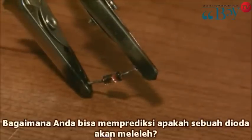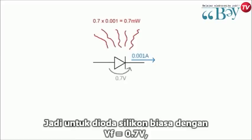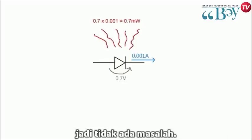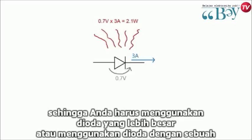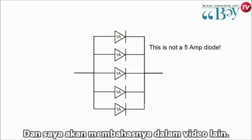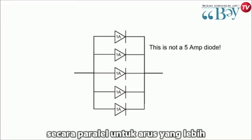How can you predict whether a diode is going to melt on you? Well, the power wasted in a diode is given by VF times the current flowing through the diode. So for an ordinary silicon diode with a VF of 0.7 volts, with 1 milliamp flowing, only 0.7 milliwatts are being lost to heat, so who cares? But at 3 amps you're generating 2.1 watts of heat, which is quite significant, so you'll either have to use a bigger diode or use a diode with a lower forward voltage like a Schottky diode, and I'll cover those in another video.